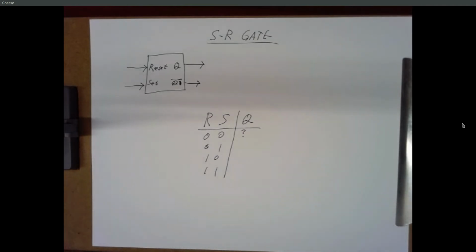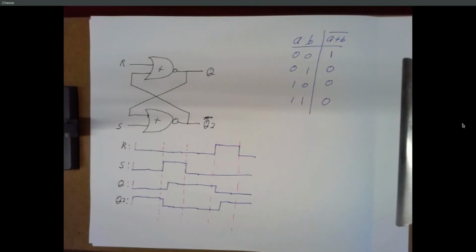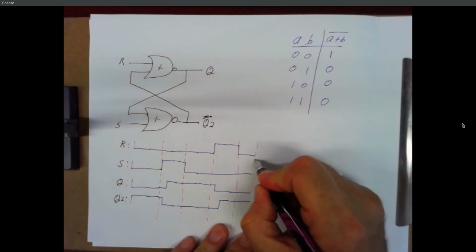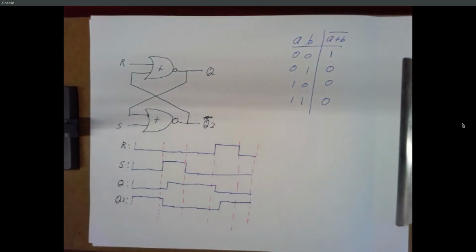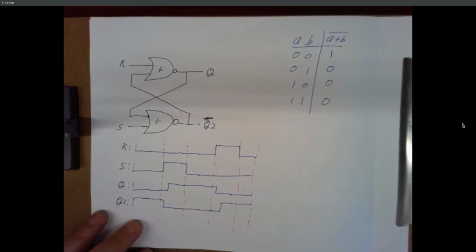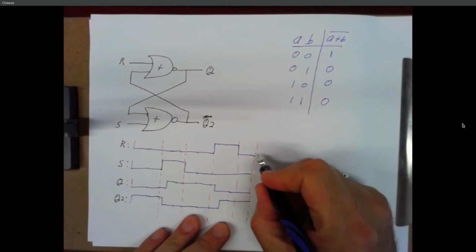Now the one thing we didn't look at in this timing diagram is what happens if S and R are both high. And that's kind of an abnormal state. Because the explanation when you buy this thing from your corner market is if you want to store a 1, raise the S line and then drop it. If you want to store a 0, raise the R line and then drop it. What if I raise both lines? Well, that's typically an undefined behavior. But